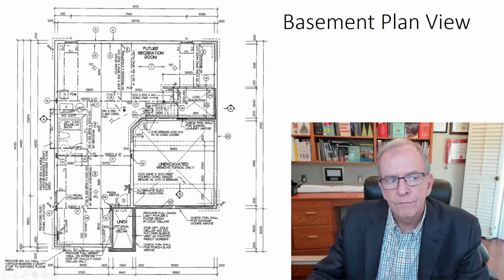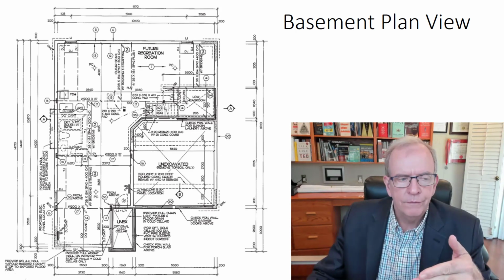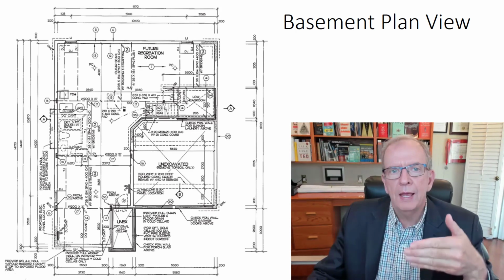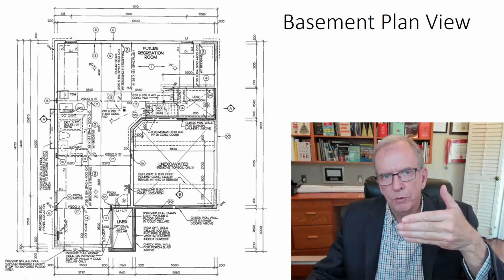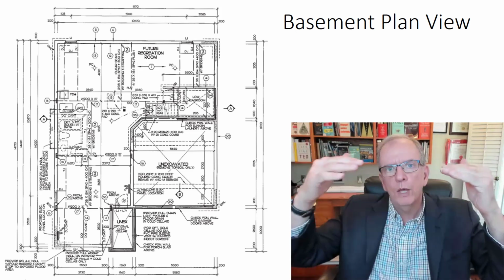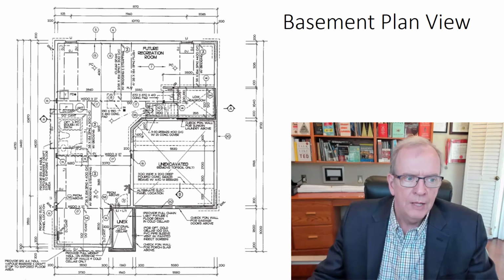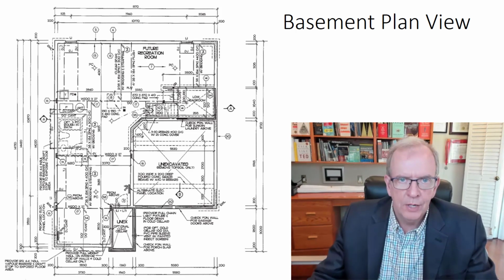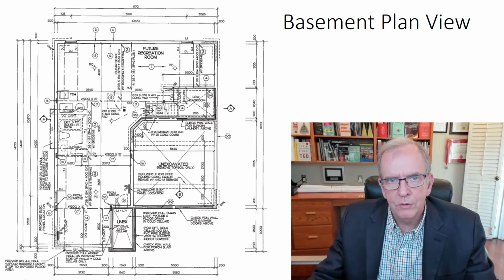Not only that, this beam, because of the way these drawings are, and we'll look at it in a future video, is supporting a bearing wall from the second floor. So it's not only supporting the first floor, it's supporting the weight of the wall from the first to the second floor, and then the weight of that section of floor on the second floor. And so it has to be designed to carry all of that weight, both the live loads and the dead loads. The live loads are when people are walking on it, things are moving around.